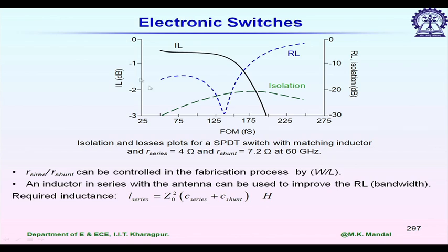Sometimes it may happen that we simply buy some switches and use them in the circuit, so the input impedance matching may be very poor. In that case, how can we improve the impedance matching? We can use some inductors simply to improve the impedance matching. So, let me show you an example.